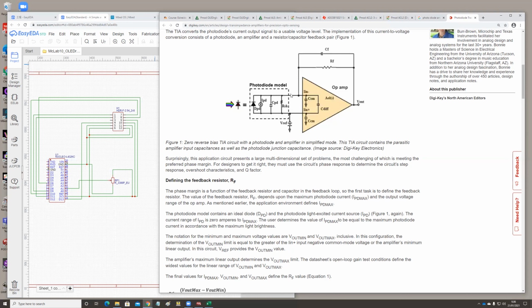And the current can't be taken from the amplifier input. It's a high impedance input. The current doesn't flow into the amplifier or out from the amplifier, but the current is flowing. Then the only way to get the current is from this line, and then the current is flowing through this resistor.